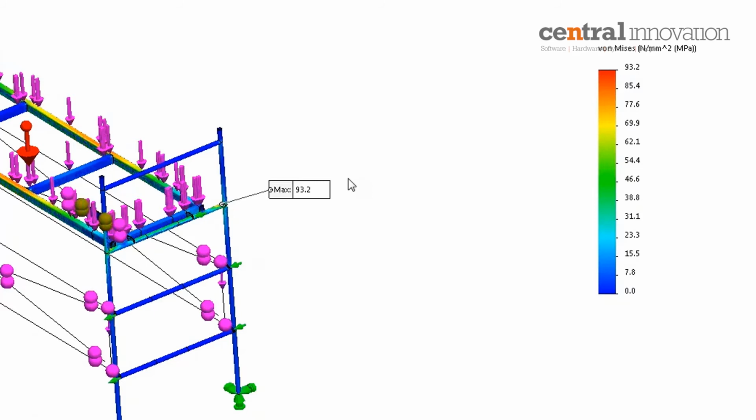And what is the structural response only if I use the working loading condition without the self weight? That is another requirement. And what if I combine both self weight plus the working load condition, and if I multiply the scale factor of 2, what is the value for that combination? I need to find that. That's why I created the load case manager.